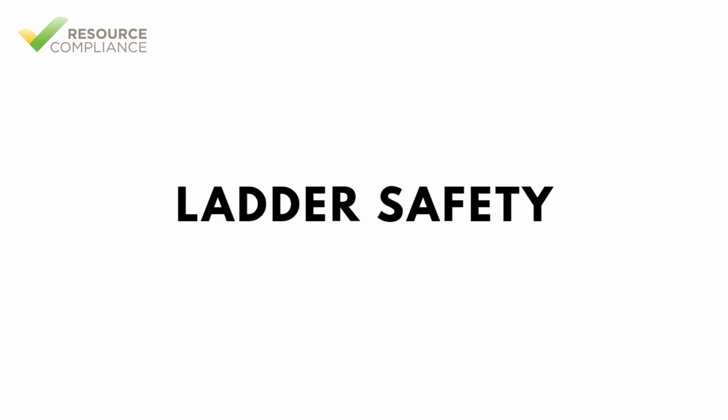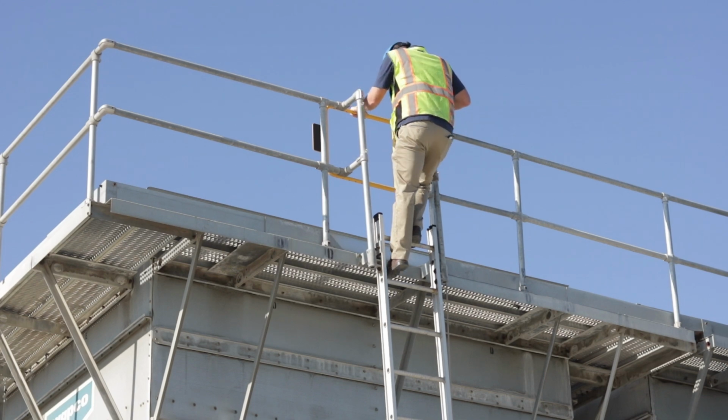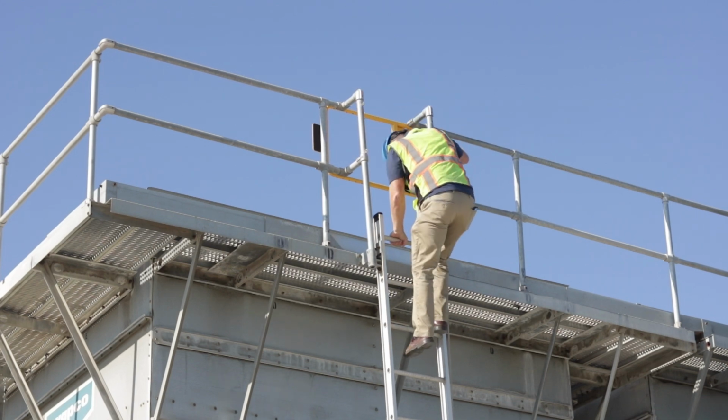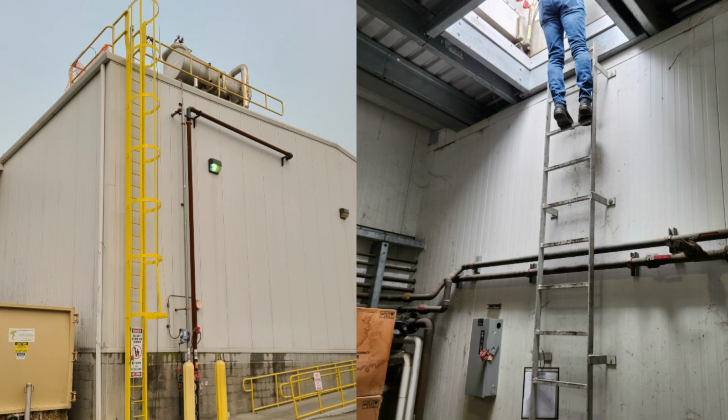Technicians frequently use ladders to access overhead valves, control panels, and rooftop units. Proper ladder safety helps prevent falls and injuries. Always choose the correct ladder type and height for the task. Ensure it is rated for the expected body weight plus any tools that will be used. Before each use, check for cracks, bent rungs, loose hardware, or slippery surfaces.